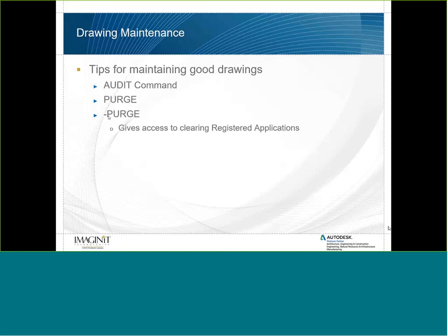Okay. A DWG file is nothing more than a very complex database, and as you add more entries to that database, there are more things it has to check when you click on things. So getting rid of those registered applications is really important on a regular basis to make sure that you keep those drawings, the file size and the extra data bloat that can sometimes end up in those DWGs down to a minimum.